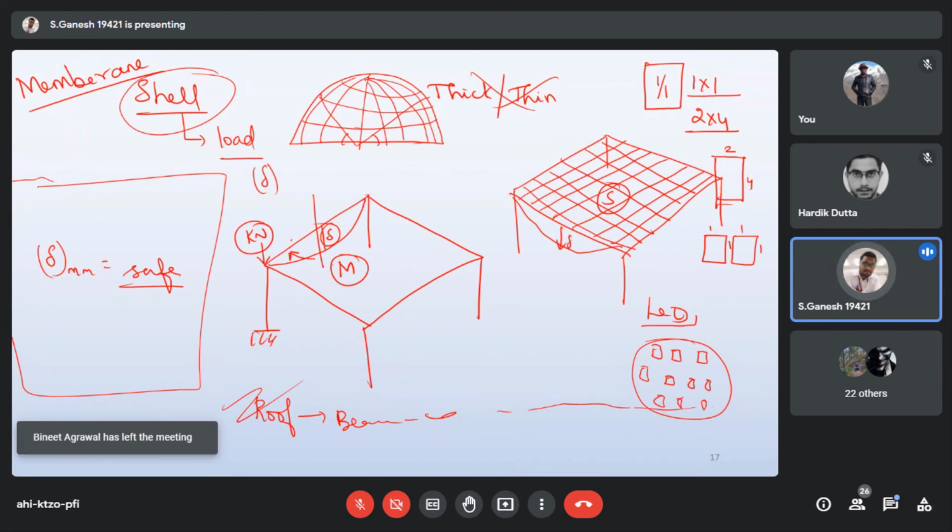Okay, Gaurav Babu: sir, how to select meshing parameters in irregular buildings? As I showed, you need to generate the surface. First, you need to create a surface membrane, and then you need to go for generate surface meshing. As I showed you in the PPT, you first create a surface, and then you do the meshing on top. Then you will get your surface meshing.